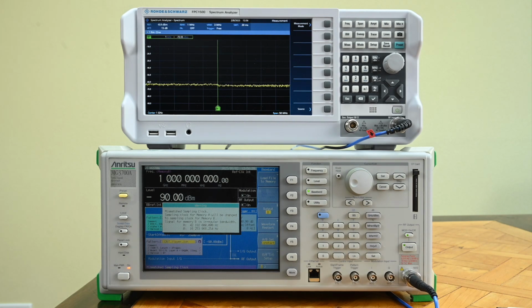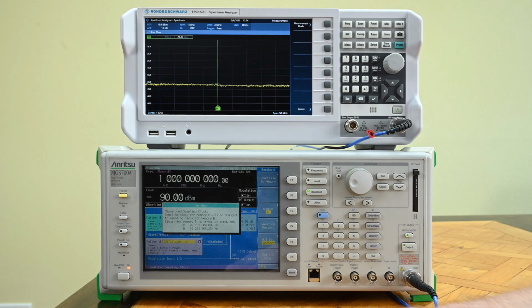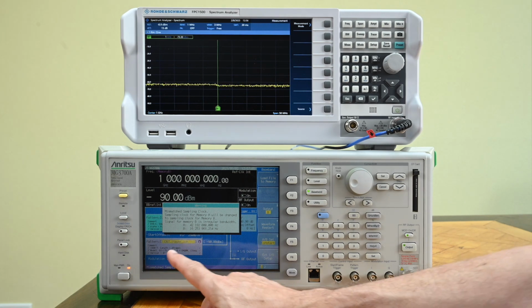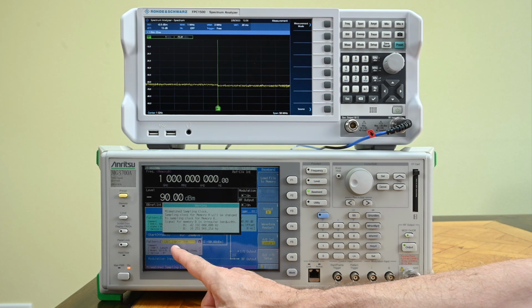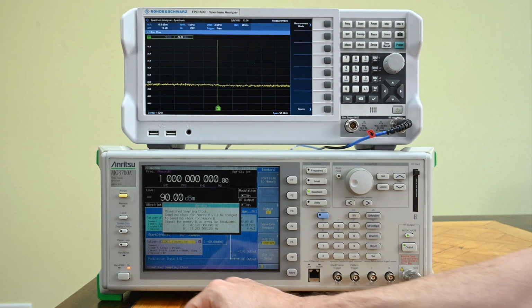This is important to understand, this error message, because what's happening right now is that we took two different source signals that were supposed to play back at a different sample rate. That sample rate comes with the waveform, and that sample rate should be correct if we want a proper representation of the signal. And since our Anritsu can only play back with the same sample rate for both of the waveform patterns, we have two options. Either we modify one of the waveforms to make sure that it goes to the same sample frequency and is still a proper representation.